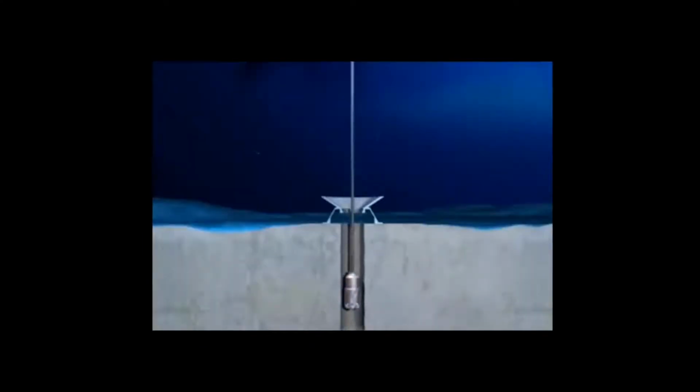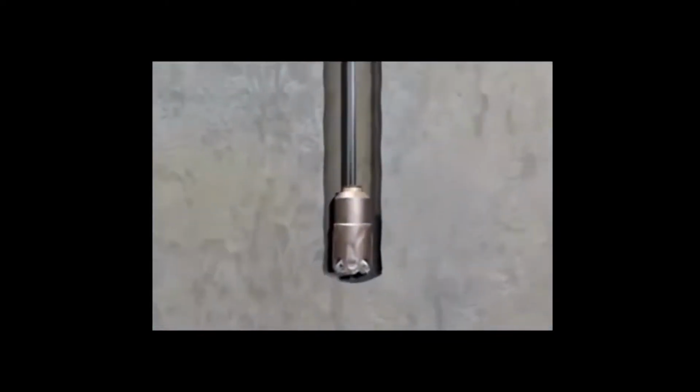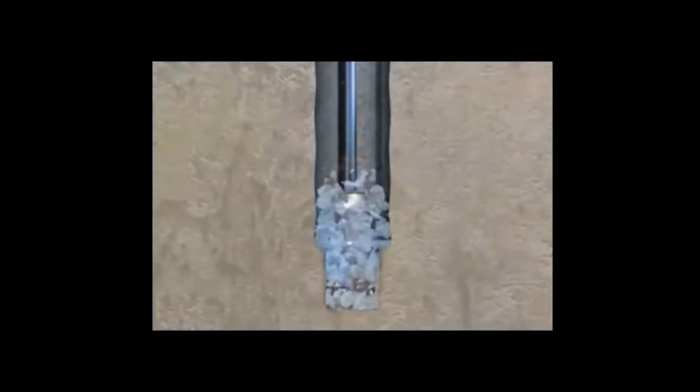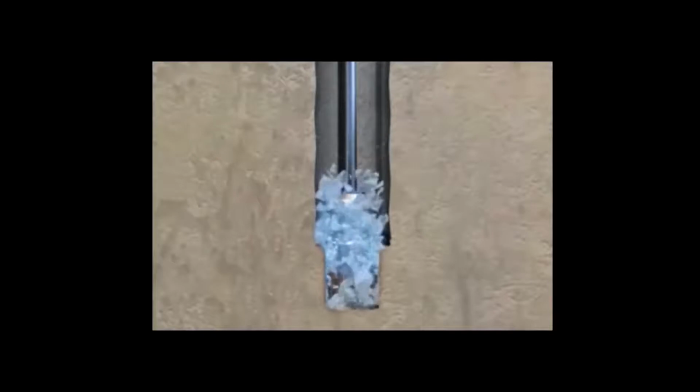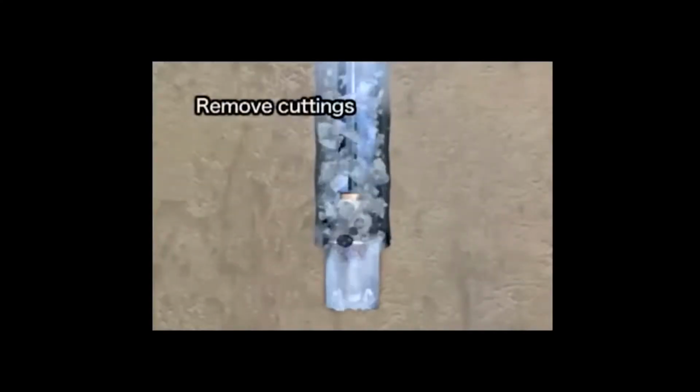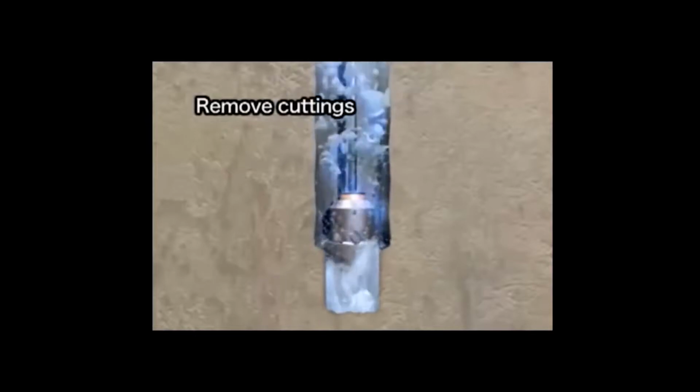With rotary drilling, the drill pipe is rotated and the drill bit at the end crushes sediment and rock to make the hole. After a while, cuttings accumulate at the bottom and drilling cannot go any further. Seawater or other liquid is then pumped from the vessel down through the drill pipe and is jetted out of the nozzles on the drill bit. This liquid current forces the cuttings up to the seafloor. That is rotary drilling.